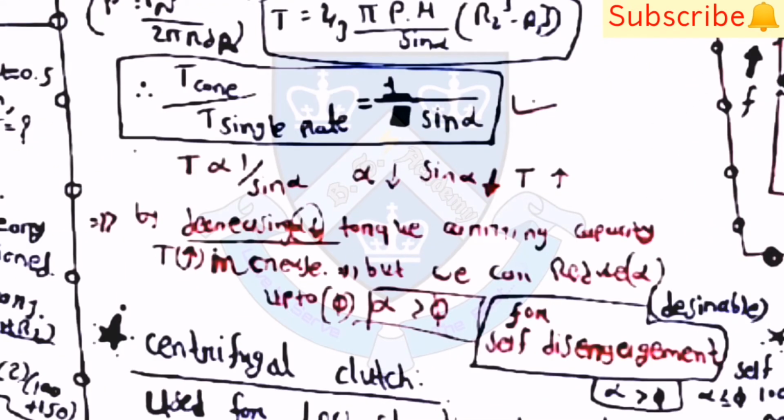Then T cone by T single plate is equal to 1 by sin alpha, so T is proportional to 1 upon sin alpha. If alpha is decreased, then sin alpha is decreased, then T will increase. So by decreasing alpha, the torque carrying capacity increases, but we can reduce alpha only up to 5, because alpha should always be greater than or equal to 5 for a self-disengaging clutch.